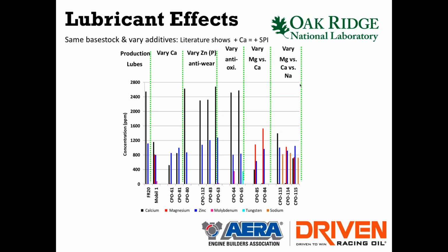It gets really complex, because a lot of the research was pointing towards the detergent package, which helps keep things clean, but detergents and dispersants also help suspend contaminants in the oil. And the detergents aren't smart detergents. They don't say, oh, that's a contaminant, and that's fuel, we'll suspend the contaminant but not the fuel.